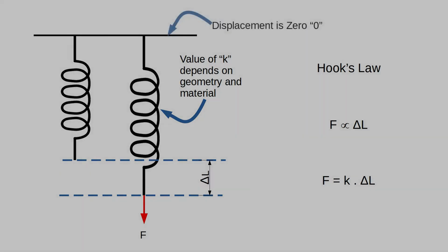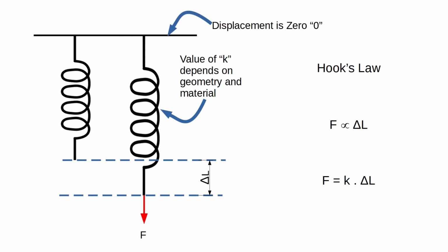The next step is boundary condition. Any given object must be sufficiently supported in the real world, and finite element analysis will simulate these supports. Either there are fixed supports, for example bolted or welded joints, or sliding supports, for example a shaft in a hub, or a pipe shoe on a structural steel. By applying these boundary conditions of support, we are providing fixed values of displacement.